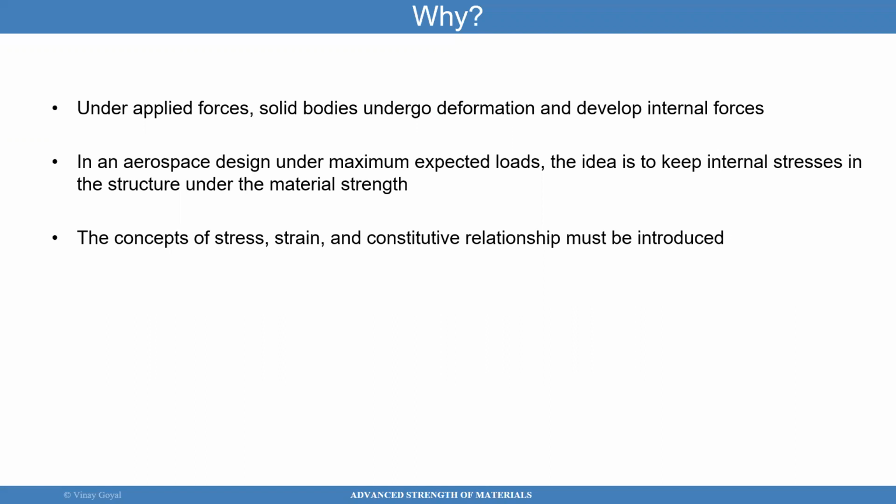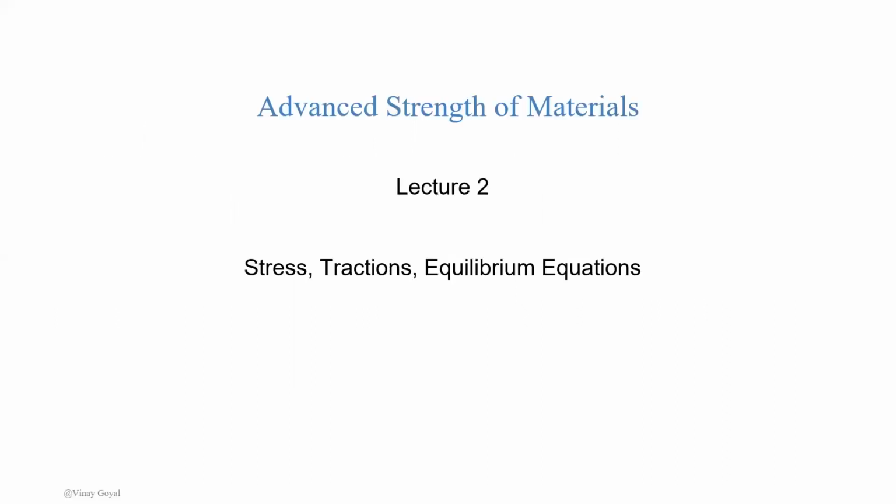And that stress then can be compared to an intrinsic material property, which is strength. Every material will have a strength. If I'm able to design a system where the stress is below the strength, then I can maybe have a good design that can survive the expected loading environments. Not the expected, but the maximum ones, right? We don't want to just design to the average load and suddenly the wind gust comes and breaks the whole thing apart, right? We don't want to do that. So for that reason, we'll introduce the idea of stress in this particular lecture.